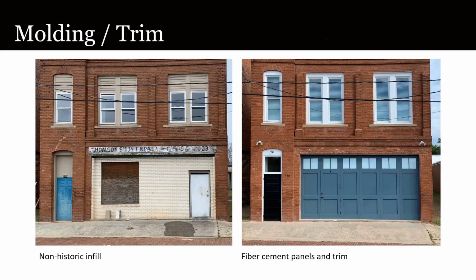Cement board may be less frequently used for trim than other materials we have just looked at, perhaps because it's not as easily cut and cannot be easily shaped or worked with typical woodworking tools as most others can. It can successfully be used, as it was in this example, where it faces the exterior surface for a wall configured to create the appearance of an early vehicular door in this historic firehouse.